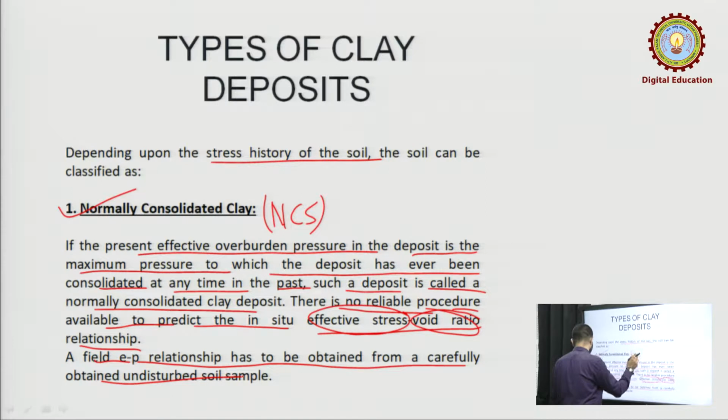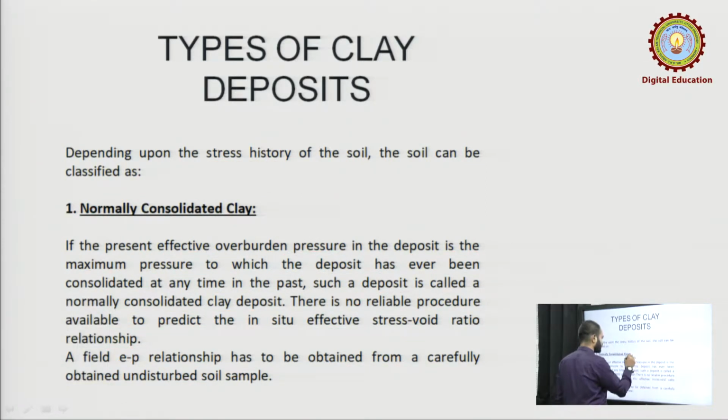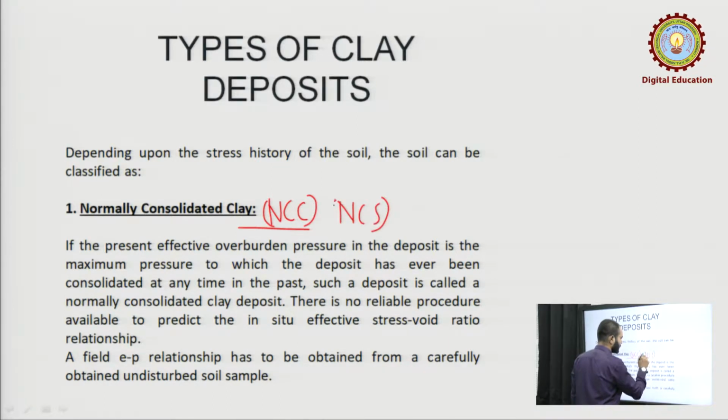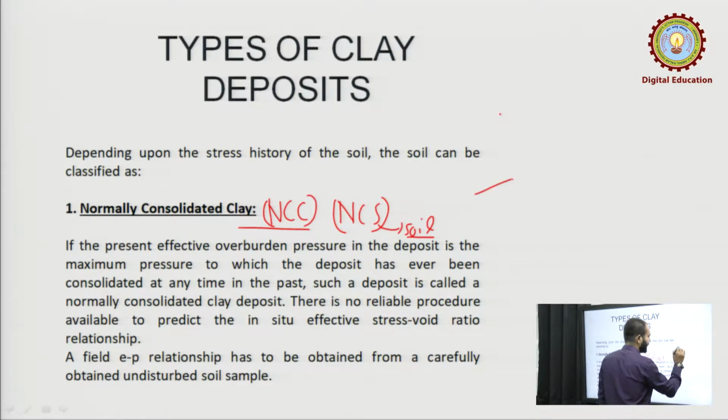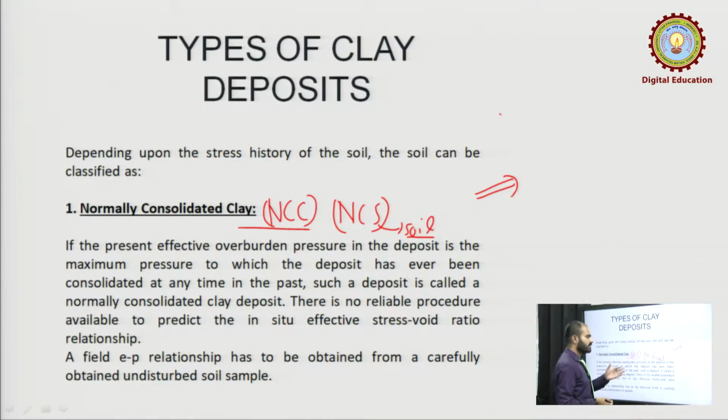I am sorry, NCC it will be normally consolidated clay, or NCS when it is normally consolidated soil. So, what is normally consolidated soil? Just now I told you, it is that soil which is stressed to the maximum, or stressed to that stress which is for the first time in its stress history.